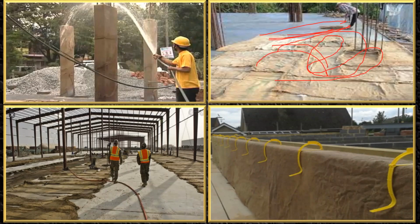The second was about the earth. Some people make use of soil and put the soil over the slab and then pour water, so that even soil can retain the water for a very long time. But again, removing the soil once the curing is done is also a very difficult task. So we don't do all those things. The simple thing we follow is the gunny bag, which is simple and the best way to do it.